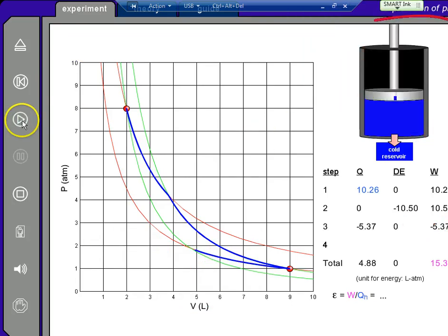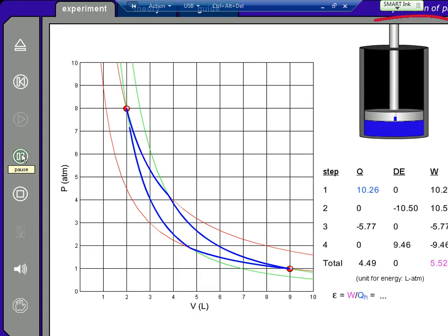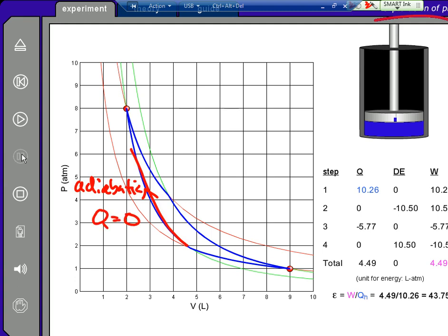And of course, for the final step, we have an adiabatic compression. So meaning that there's no more heat loss. And for this portion over here is adiabatic. So Q equals 0, but we still end up with positive work. Okay, so this is something that needs to be memorized. And overall, we have our 4 steps for our Carnot cycle.